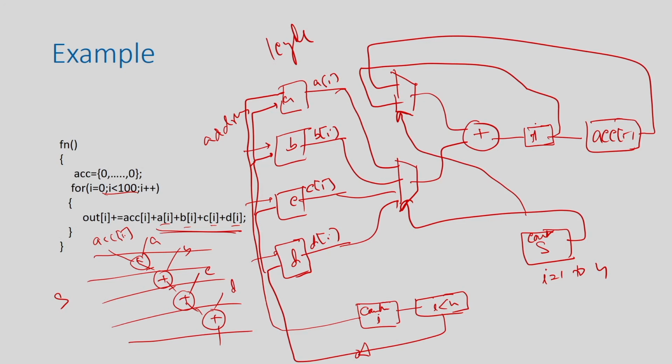So, what is happening in the first clock, you read all those things. So, the read will be done in say first clock. In the next clock, you are actually performing this SCC plus AI, right. So, this mux will select SCCI and this will select AI, and that summation, this result will be stored in this T, right. And then in the next clock, this S will decide, and this counter won't increase until. So, this counter is basically N into S, right.